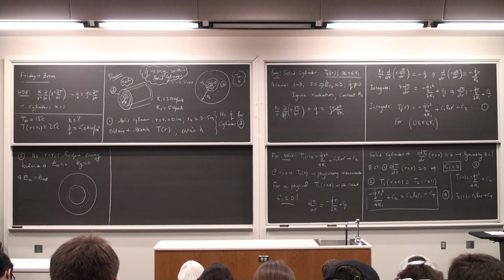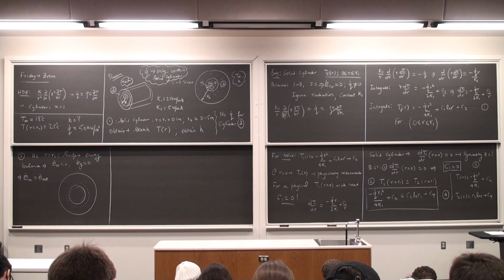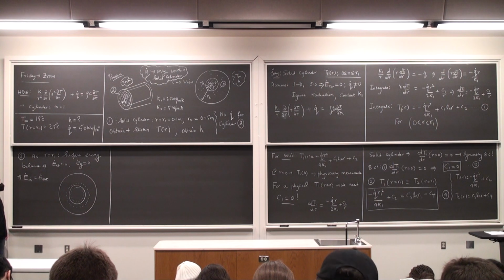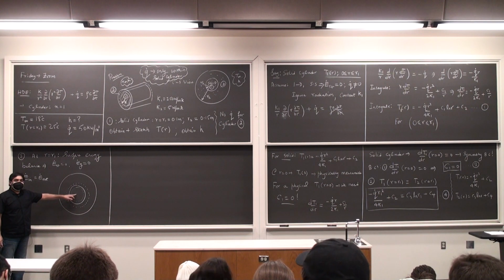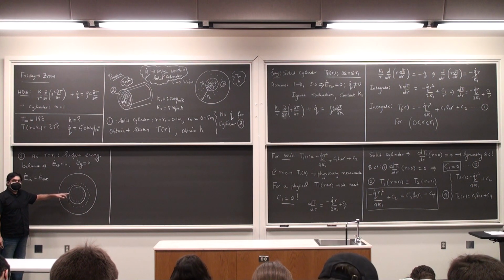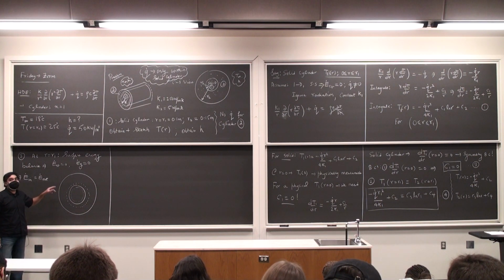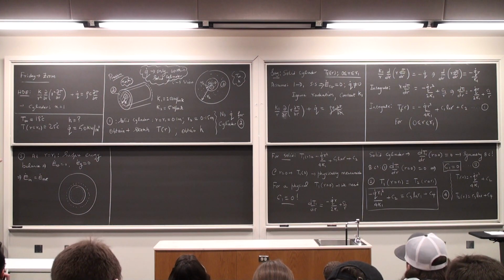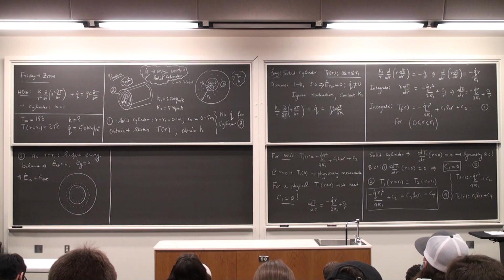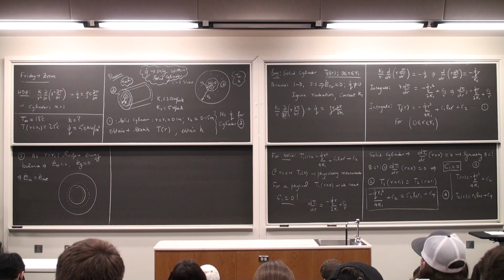Okay, so this is my control surface. There is great suspicion that the heat transfer is obviously going to take place from the center here all the way through to the radius R1 and then to the radius R2, because I know that the temperature at R2 is 25 degrees, temperature outside is 18 degrees, heat can only travel in one direction.